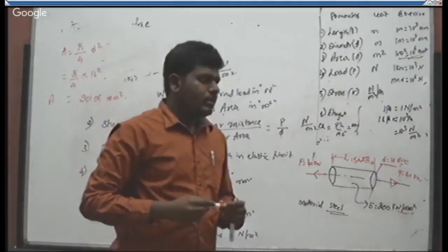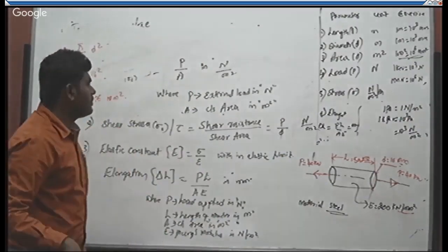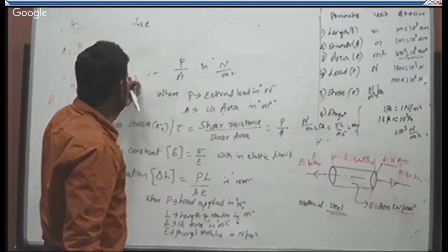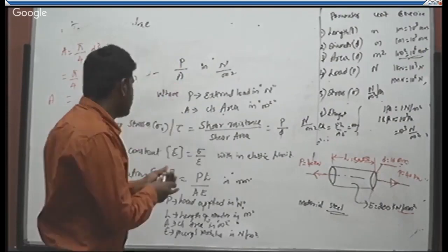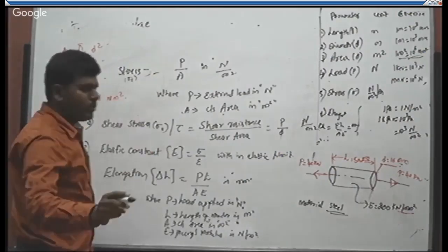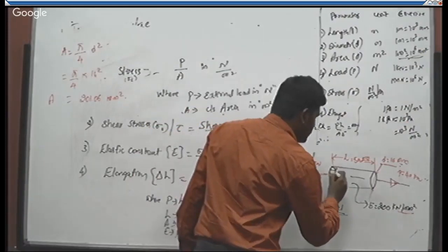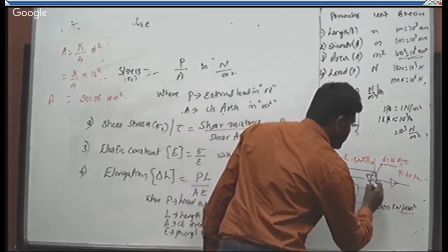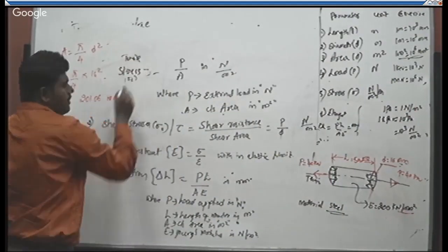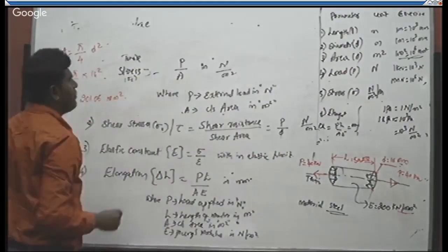Okay. So next, look at the formulas. So how can we find out the stress? We have the load and we have the value of area. Then simply we can use the stress is equal to P by A. So here the induced stress, because the load acting is the tensile load, the stresses induced opposing this action are tensile stresses in this case. The types of stresses induced are tensile in nature, which is given by P by A.